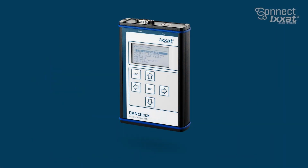Issues at the bus interface, like a defect transceiver or poor signal quality, can significantly disrupt the communication. Using tools like the Ixxat CAN check to assure that the voltage levels and the recessive and dominant CAN signals are correct can diagnose these problems effectively.